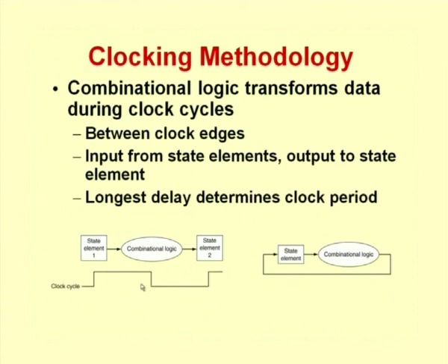Of course, we will look at other designs where, if this takes too much time, we can also have multiple clock cycles. But to start with, assume that I am designing my circuit as one state element, then some combinational logic, then a state element, then a combinational logic and so on. Typically, whichever combinational logic takes the longest amount of time, you will fix your clock period as equal to that longest amount of time. So, this is one factor that we normally use.